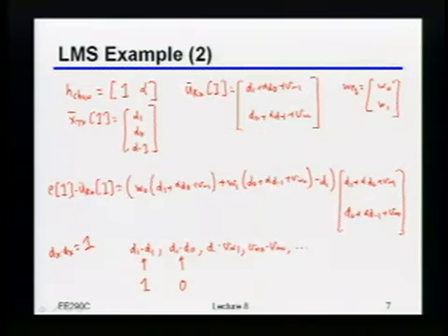Okay, so how about D1 times Vn1? What should happen there? Yeah, it should also be 0, right? Because the noise, hopefully, is very clearly uncorrelated with the data. So that should also get filtered to 0. How about this Vn0 times Vn0? What should that become? Noise variance. Yeah, this just becomes the noise variance. And in fact, even if you have terms like Vn1 times Vn0, that's just something like the noise autocorrelation at a one sample time shift, okay?